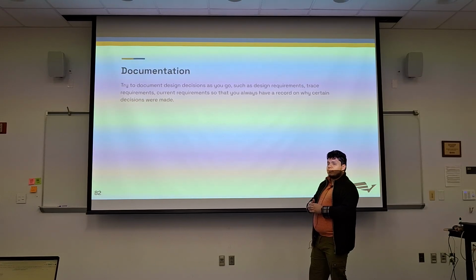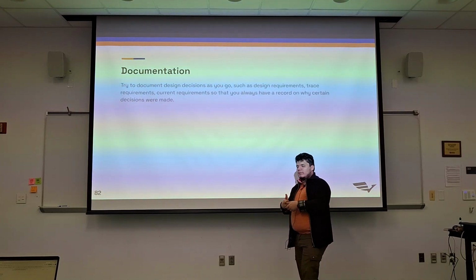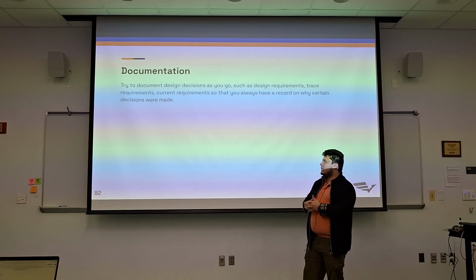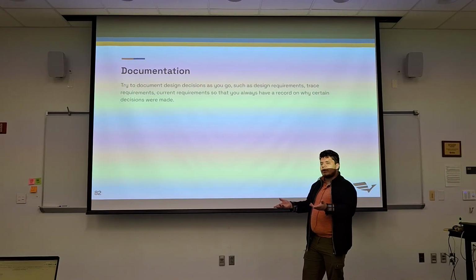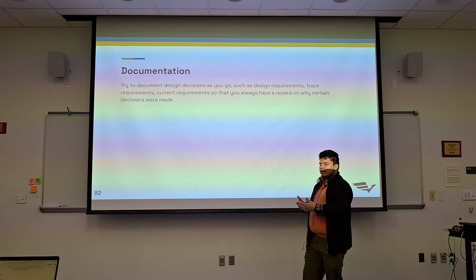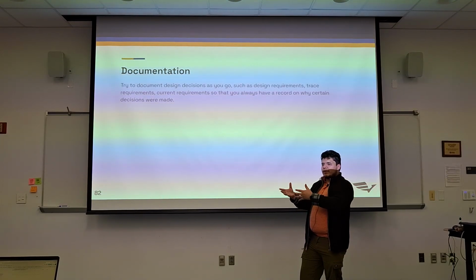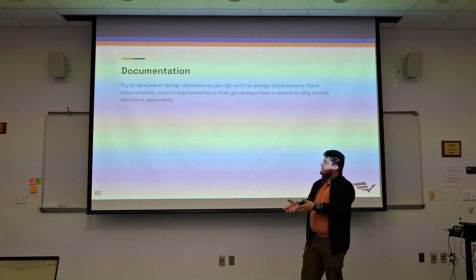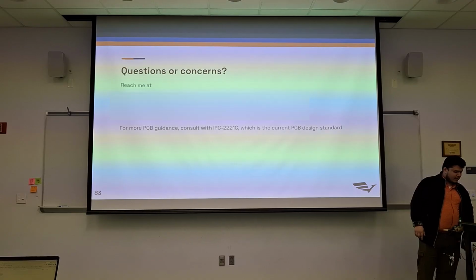It's also going to make it easier when debugging. Whenever you actually get to build the design, you might not be the one overseeing that testing. Hopefully you are. If you design it, it'd be nice for you to also test it. But if someone else is testing it and notices some discrepancy, like, this should actually be 120 ohm differential, where was this decision taken? Why am I seeing so many reflections coming out of this component, out of this IC? Is this a problem with the IC, or is this a problem with the PCB design? And so always try to keep a good record of every decision that is made.